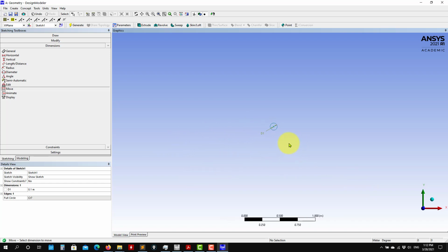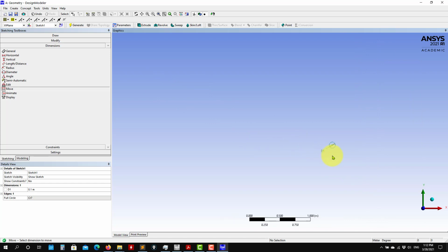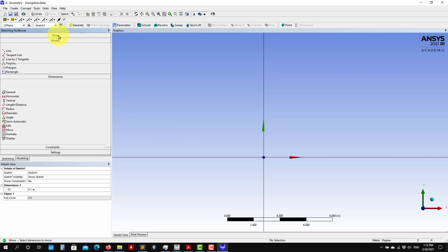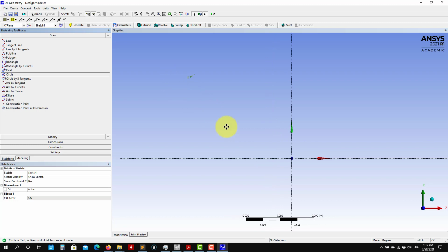One thing that is important for the height, for setting up the CFD simulation, is that it doesn't matter where you put this origin. But my advice is to always put it at 0, 0, 0, to center everything. So look at that, I put it there. And now I want to put another circle concentric to this one. Just to show you something, I can draw another circle, and see that when I move, you see that P there. P means that that one is centered with the origin, with that point. It can be this origin or a point that you have there. C means it is on that line, so in this case centered with the axis line, but it can be with any edge that you have in the geometry. I could have drawn everything like this, but I put it there just to show you how to add the constraint.